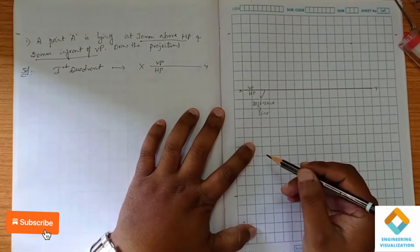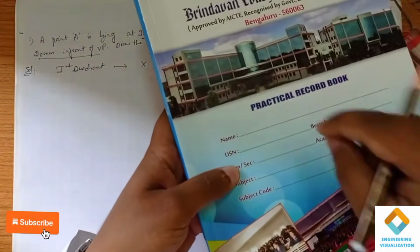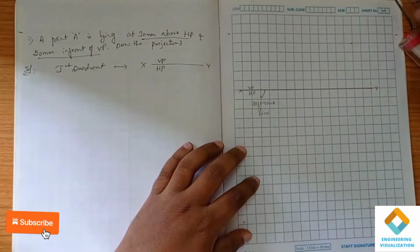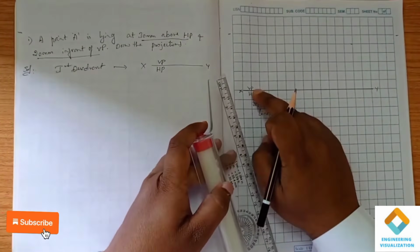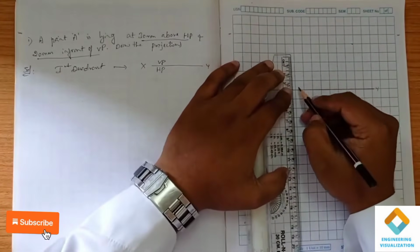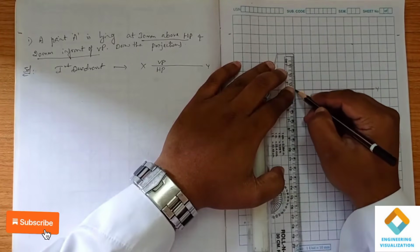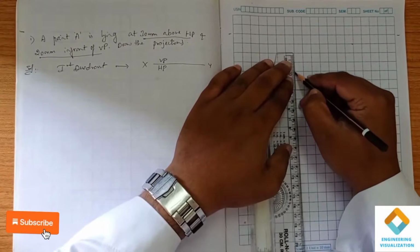We know that if any point is lying above HP or below HP, it means it is a front view. Okay, so the front view will be drawn in the vertical plane. So the vertical plane is lying above the XY line. So initially we draw 30 mm. So 30 mm means 3 boxes here. So we can count the 3 boxes. Directly draw a projection line. Okay, we just draw to this line.